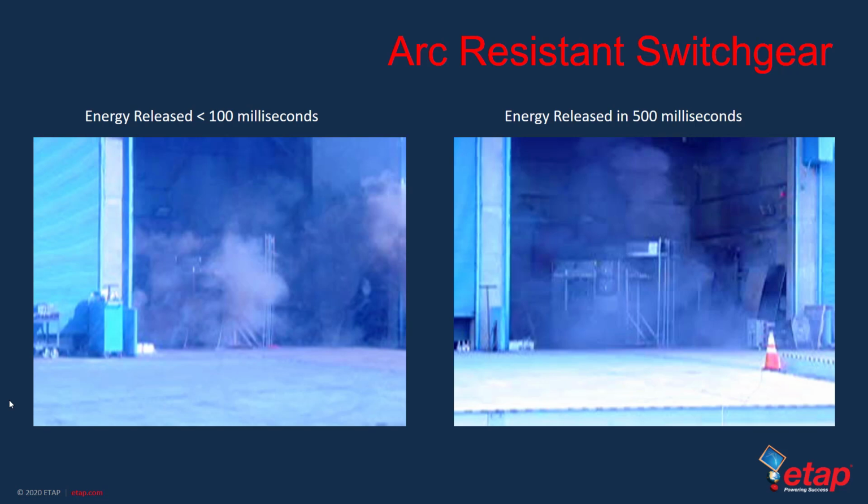Also, if the arc energy inside the equipment is too high, it may prevent placing the equipment back in service with a basic cleanup and reconditioning, as is expected for arc resistant equipment. The most important takeaway from this video is that energy is proportional to arc duration, or time, and current, and if either parameter is too long or too high, then the arc could exceed the equipment kiloamp cycle rating.